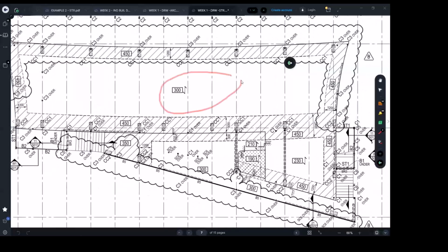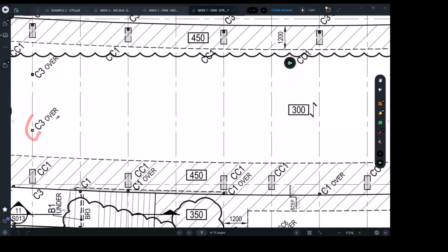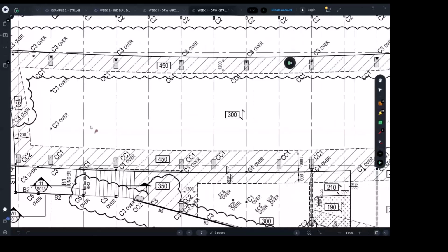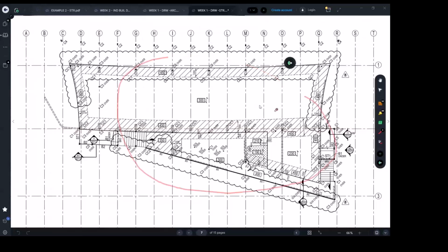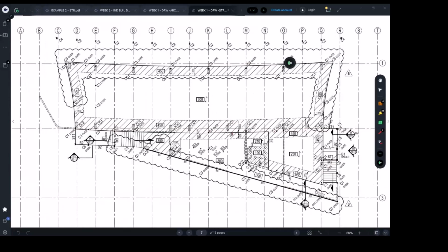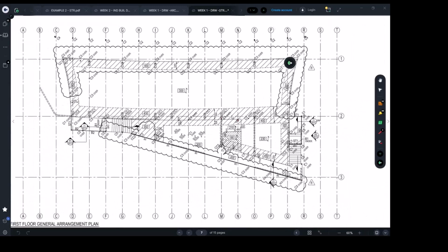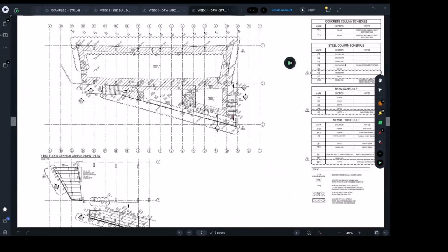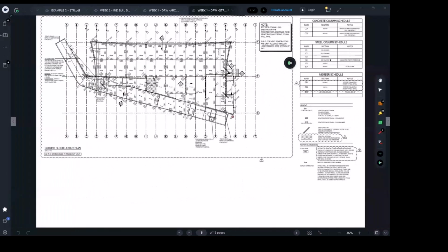Then the ground floor load, in addition to the roof load, gonna go through the band beams or the slab, whatever the case was. So you got some columns actually sitting on the slab, so the slab will worry about it, right? So those the dead weight and the live loads from the roof and the first floor gonna be supported via the band beams or from the slab to the band beams, and then goes where? To the concrete columns, CC1s, right? Then CC1s will take all the load towards where? Can someone answer this very last question? CC1s will take the load where? Footing. The footing, that's it.